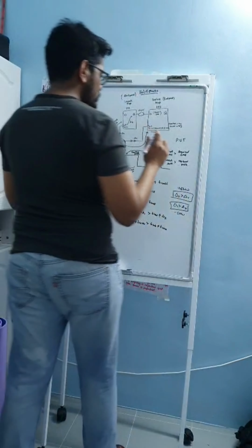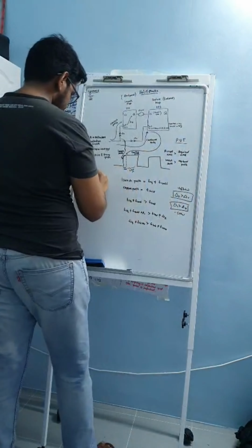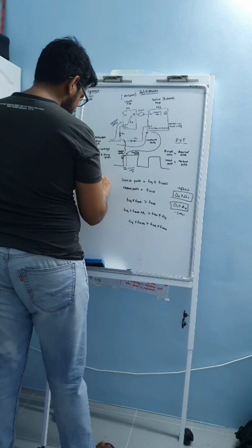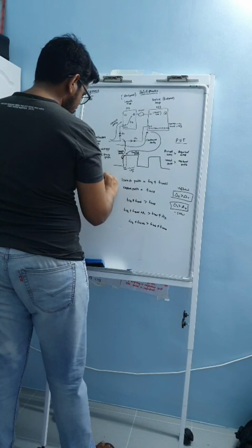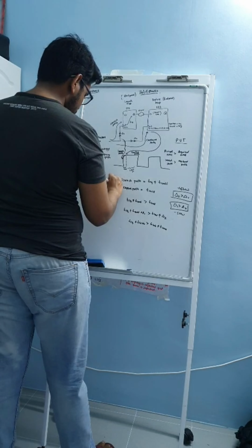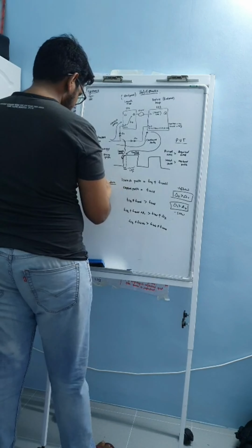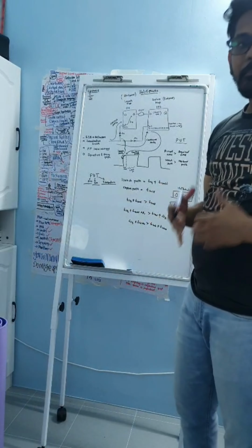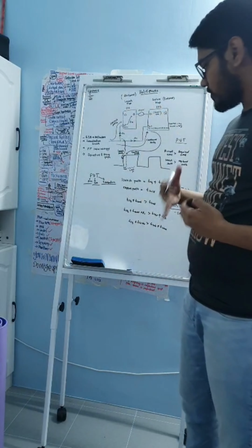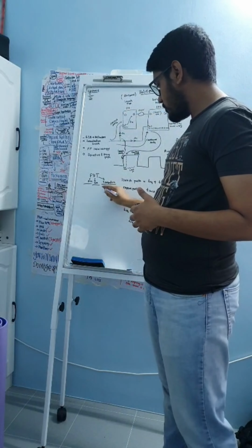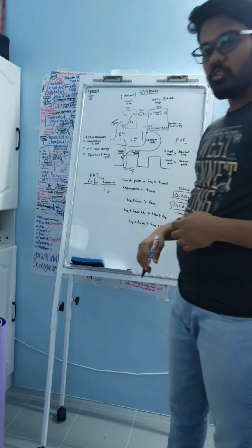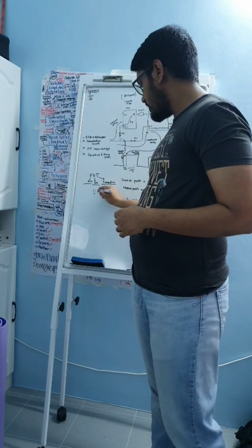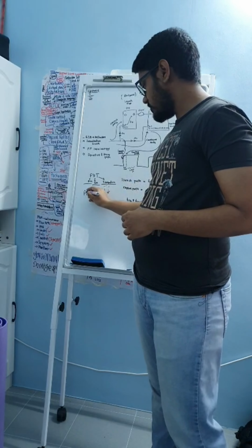Moving on to PVT, let's talk about this. This is process, voltage, and temperature. On this part, we want to have the best performance for the data path. Whenever you want the best performance, you have to make sure the temperature is colder or lower, your voltage is increased, and the process is fast.